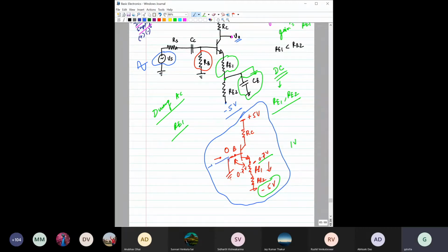See, we are applying this RS and we are applying here this VS, right? If this is VS, then what is the voltage? This signal is basically always applied across this, right? And no part of the signal is appearing across this base terminal, isn't it? Yes, you are right. So to use it for an amplifier, yes. So VS can go to ground even when RB is present.